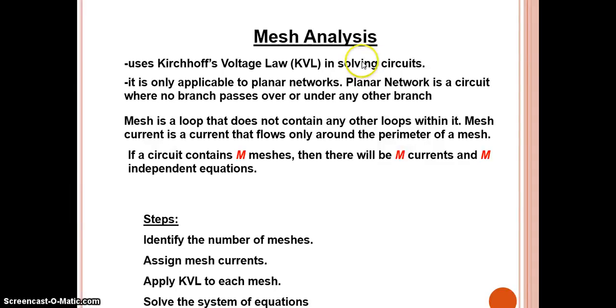Our next topic is mesh analysis. Solving a circuit using mesh analysis is based on Kirchhoff's voltage law. What is Kirchhoff's voltage law? The algebraic sum of the voltage drop across each element in a closed loop is equal to 0.